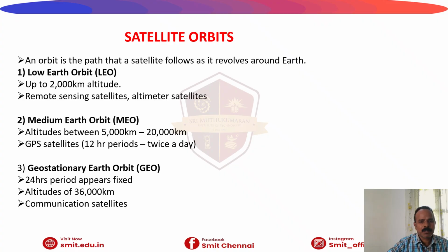In the last session, we talked about the various satellite orbits, that is LEO, MEO, as well as GEO. So the LEO is generally positioned around 500 to 2000 kilometers altitude. It exhibits a much shorter period, that is up to 95 to 120 minutes only. The LEO satellites provide very high quality communication, but the biggest problem of LEO is the need of many satellites to provide global coverage.